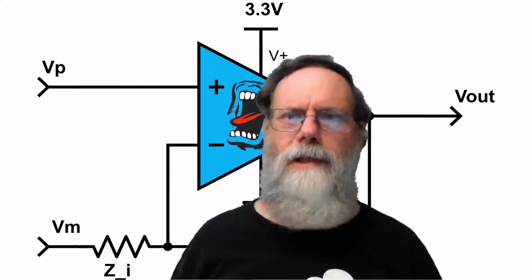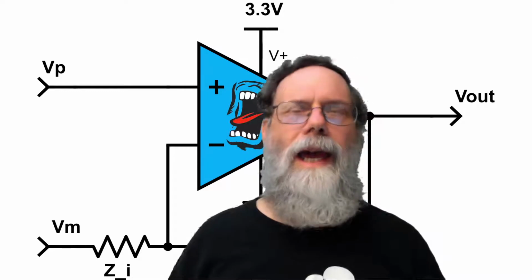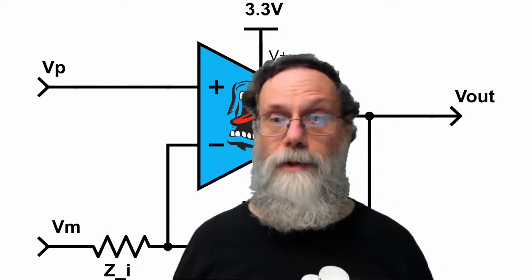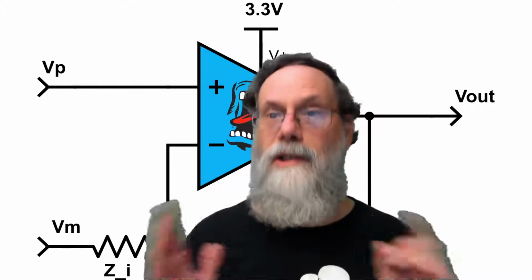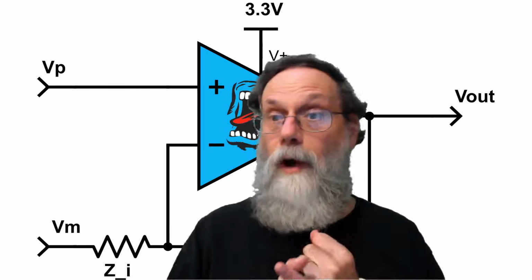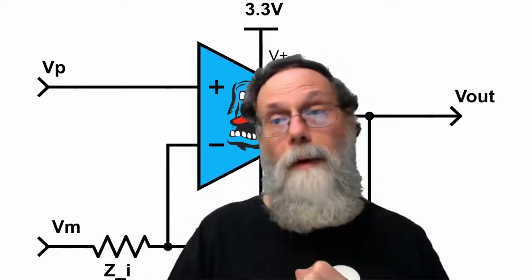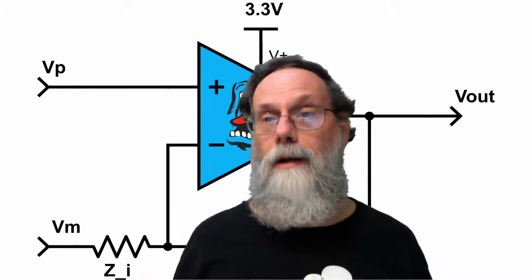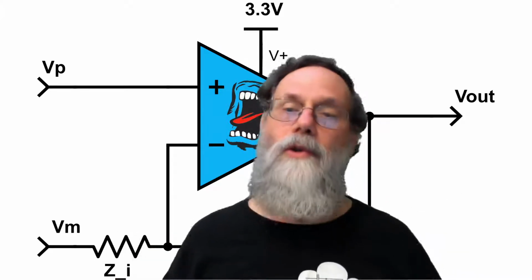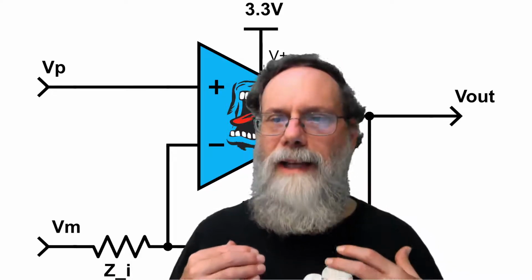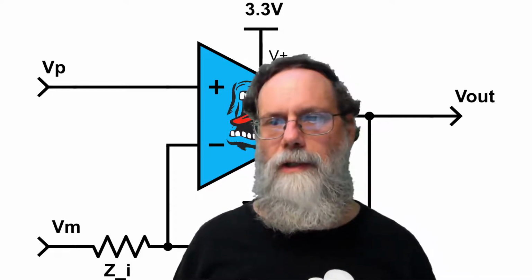Well, 200 millivolt signal multiplied by the gain of 1,000, and I get a 200 volt signal coming out. Now, wait a second, my power supply isn't 200 volts. I'm not going to get 200 volts coming out. Something's wrong. That's a sanity check going, okay, was I wrong about the gain of the amplifier? Was I wrong about my power supply? Was I wrong about the size of my input signal? One of those things is wrong because they're not consistent. So doing consistency checks like that is an inherent part of any sort of engineering design.